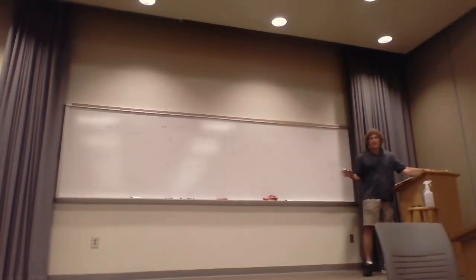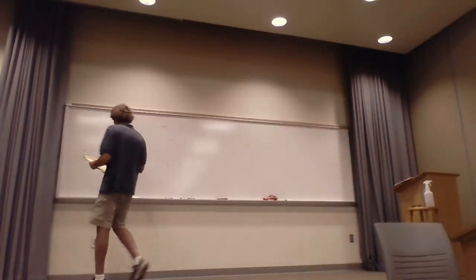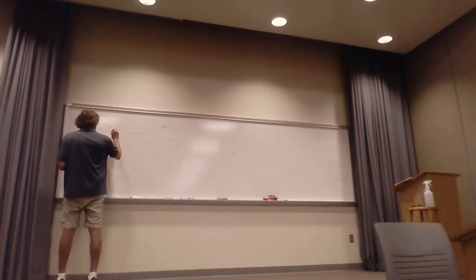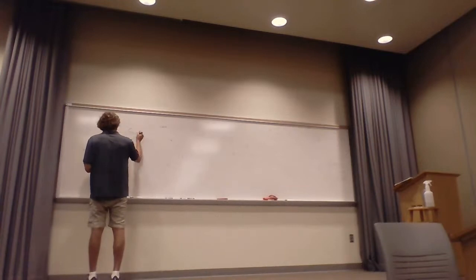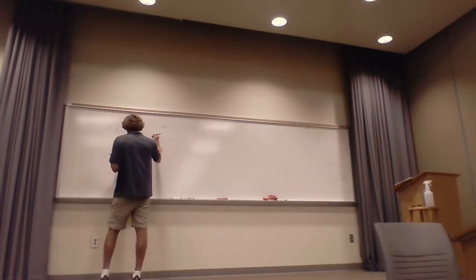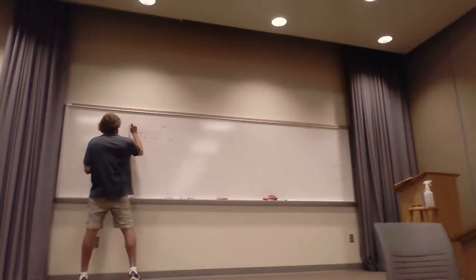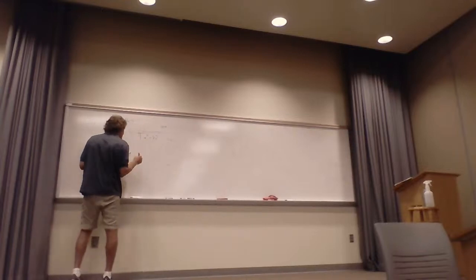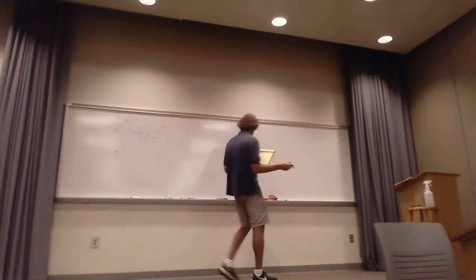But anyway, the requirement, and the way he puts it, to have only one mode, and that's what you want, is going to be, and he does it this way, A over lambda naught is less than 1/2 times something with the index of refraction. So it's the square root of n1 squared minus n2 squared. And this is assuming mu relative is equal to 1, and it's not lossy. This can also be rendered as A over lambda naught.